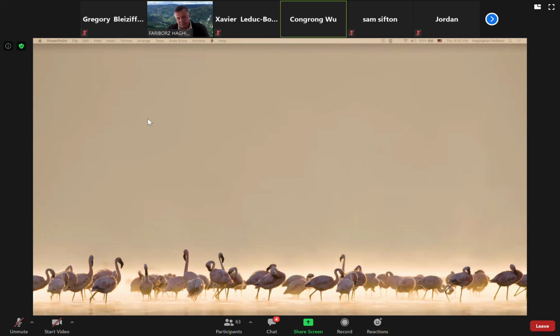Sir, to my understanding, we analyze each wall for different layers. No. You're in a house, sir. You're in a room. Therefore, you have to do it simultaneously, all of them at the same time. You cannot write one set of equations for each wall and solve them independently. East, west, south, they are integrated together because they are linking the room together.